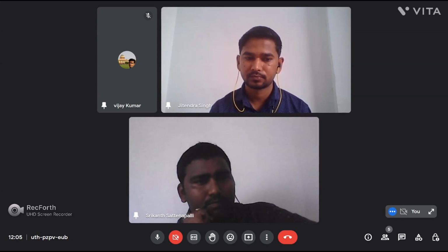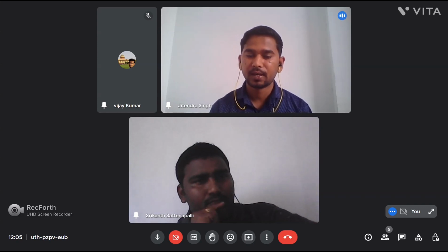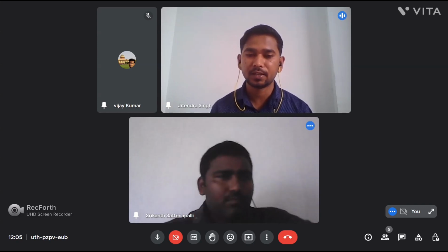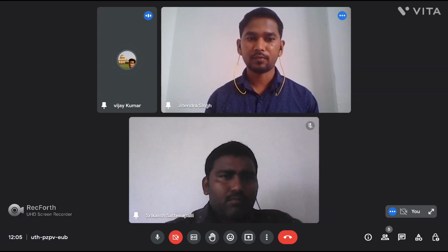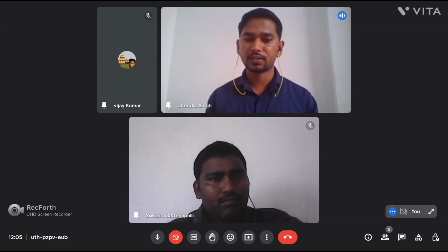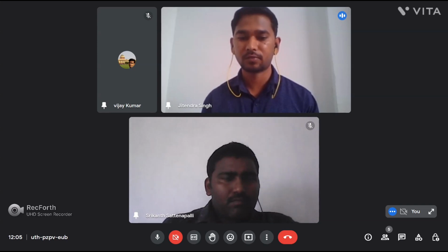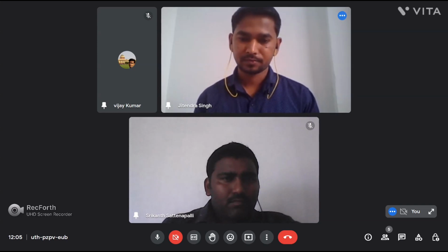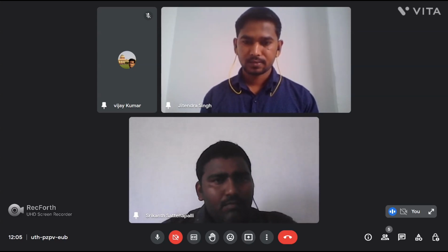That is the unit. What will happen if the baud rate of the transmitter and receiver is different? So there is no transmission between them. We have around 10% tolerance of baud rate. If we have a 10% difference between the transmitter and receiver baud rate, it is okay for the UART. Beyond that, it is not working.